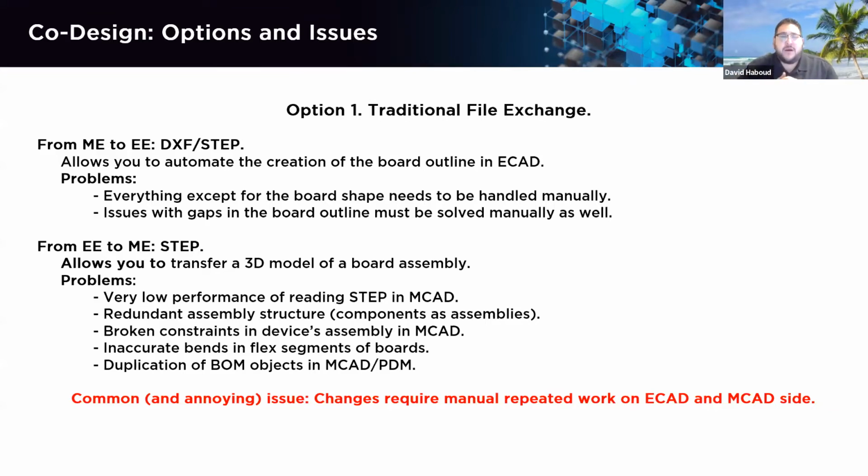Big problem here is that the board shape needs to be handled manually. There's issues with gaps in the board outline. Again, this needs to be handled manually. A huge issue that you'll see here for both sides, I guess I'll wait to talk about this, but let's go to the next step.